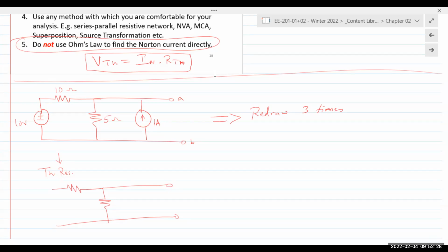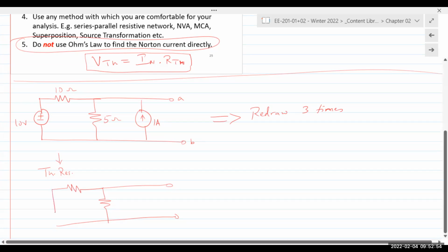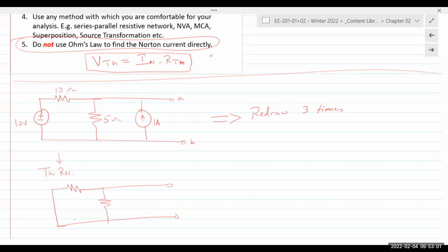Okay, it only applies to the Thevenin resistance circuit, does not apply to the voltage or the Norton current. If you remove the sources when you're trying to find a voltage, if there are no sources in the circuit, what are you going to get at the output? Zero. You won't get anything. Okay, so reducing a source, I mean shorting the voltage and opening the current, only applies to Thevenin resistance, does not apply to voltage or the current. So the voltage source is shorted, the current source is removed. And this would be the setup of the circuit.